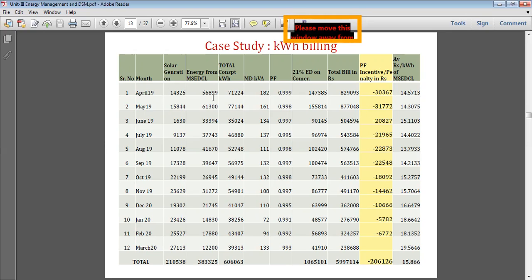So it is found that the maximum demand occurs with a seasonal variation in the temperature also. In April, May, the maximum demand is more, whereas in January and December, the maximum demand is smaller. Okay, so here it will indicate the maximum demand. Maximum demand is nothing but the simultaneous loads connected to the system, or simultaneous loads in operation, for any one type of consumer.